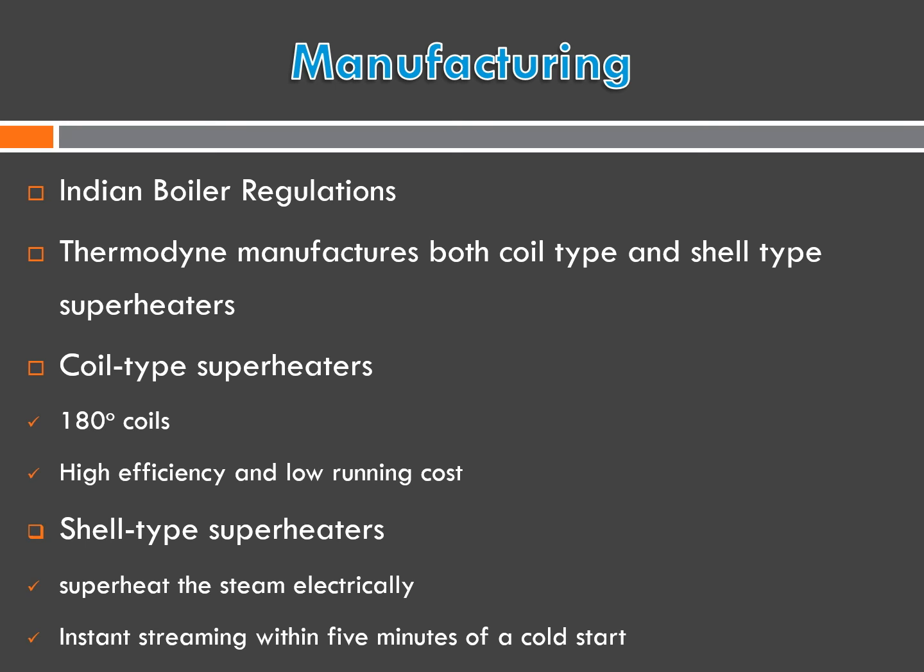The IBR was created in 1950 to enforce certain regulations which need to comply with the Indian Boilers Act of 1923. It includes the boilers, the feed piping from the discharge side of the feed pump, and steam piping up to and including the stop valve of the steam consumer and attached fittings or vessels. It also has steam receivers, separators, steam traps, accumulators, heat exchangers, converters, evaporators, and many more.